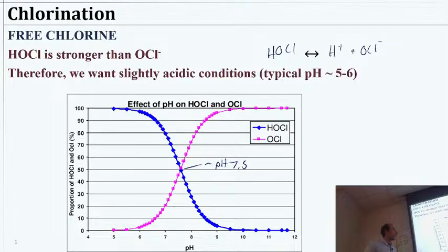So that means if we had, in our example last time, the pH 6, I think it was, for the poliovirus, we would see that something like 97% of the chlorine was in HOCl, whereas a small portion of it would be in the OCl minus. And that becomes very important in scenarios where we may have a sizable fraction of our chlorine in the useless kind, the OCl minus.